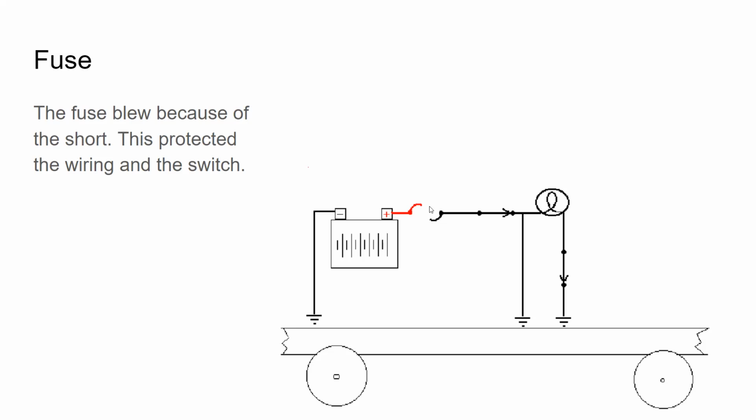The fuse is a very short duration light bulb. When it pops, it makes a flash, like an old-time camera flash. But if it's doing its job and everything's designed correctly, it'll pop, it'll interrupt the circuit, and it will protect the rest of the wires. If we have a short circuit and it blows the fuse, you might not know there's a short circuit going on in your car. All you know is something quit working, this bulb, and you might look in the owner's manual, figure out the fuse for it, and put a new fuse in there.